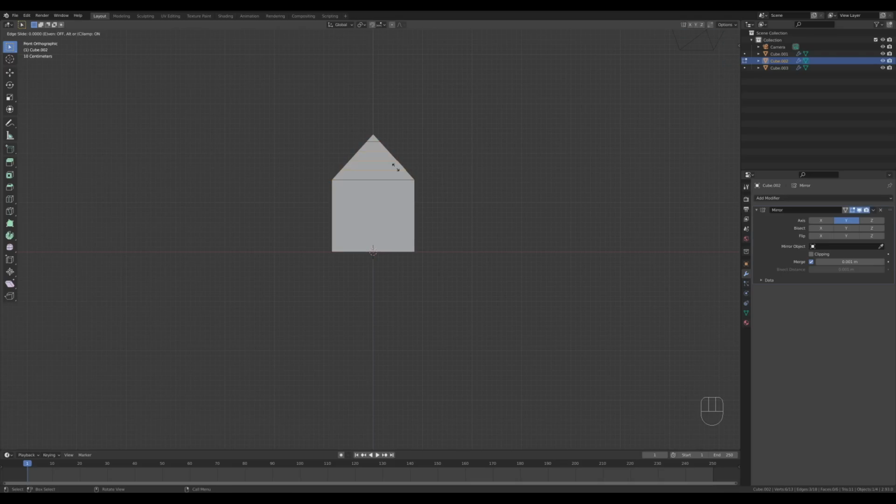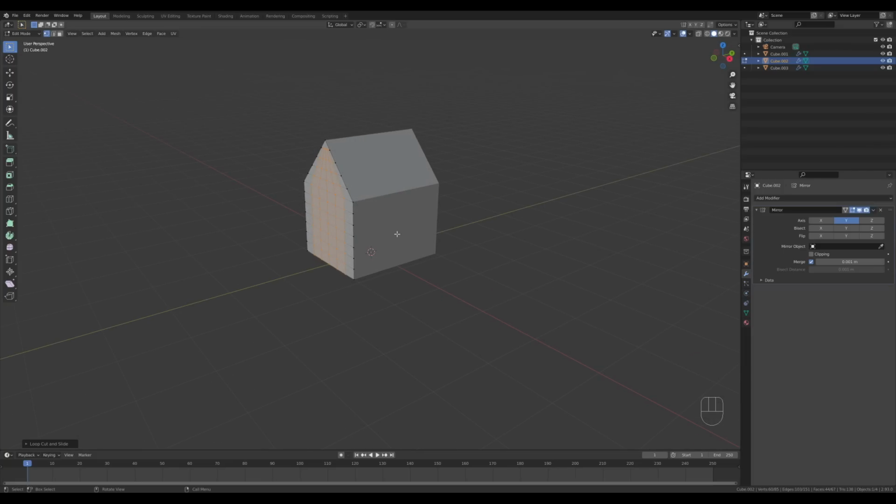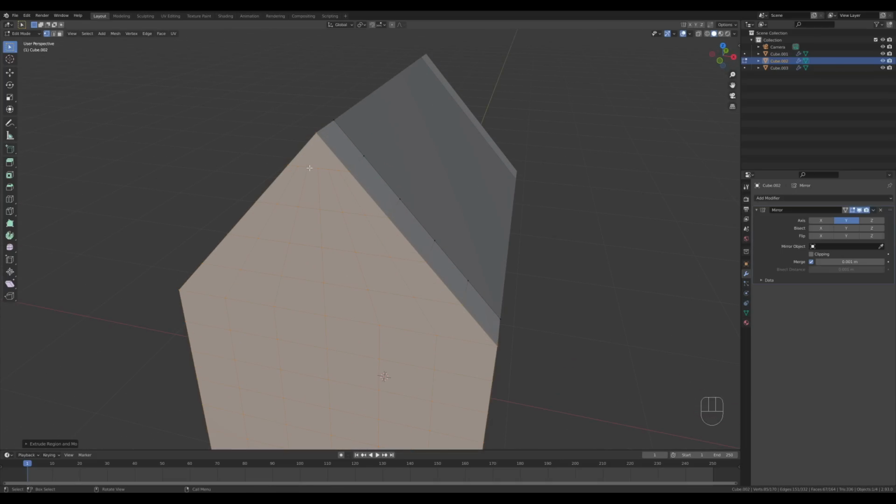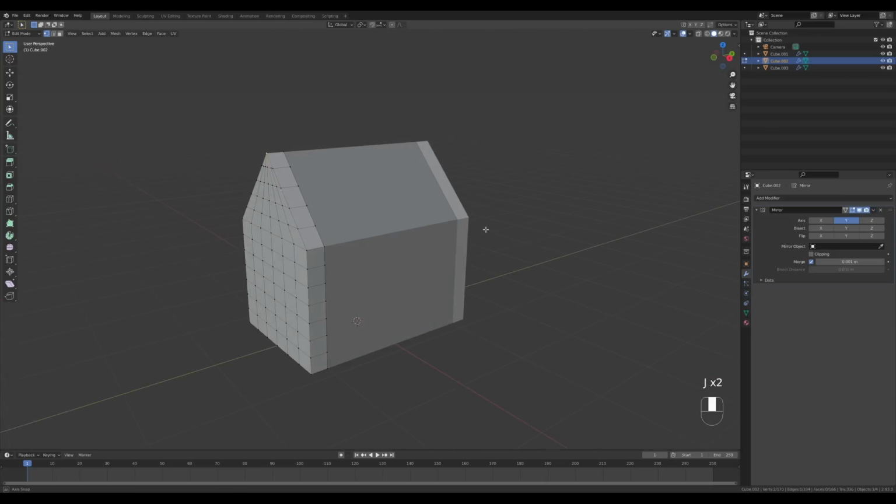So press Ctrl R and create like 3 subdivisions there, and we'll do similar here, right click to release. And now let's do some of these vertical loop cuts. Okay, that'll do. So now press A to select all and just extrude this. Okay, this should work. And we have a little angle here, so to make things a little bit easier on the subdivision modifier, we can just connect some of these to give this a little bit more geometry.